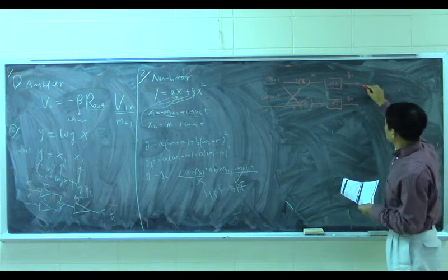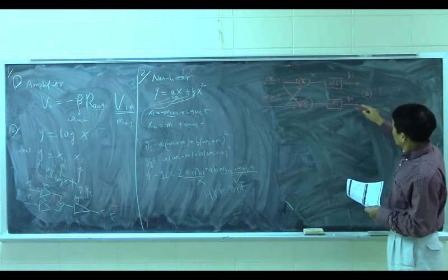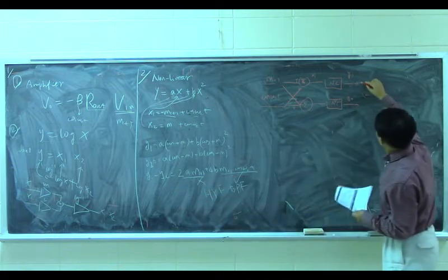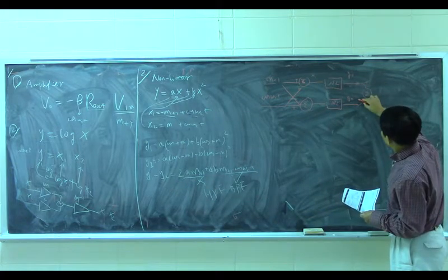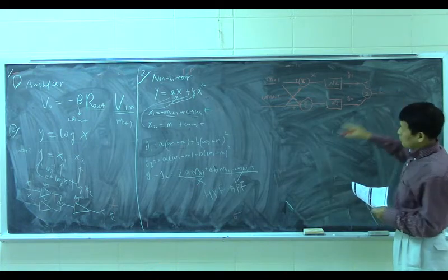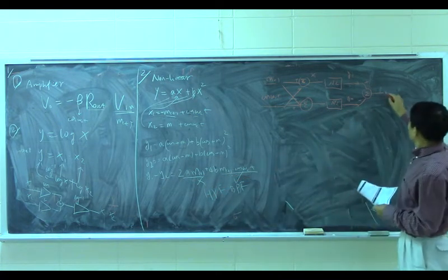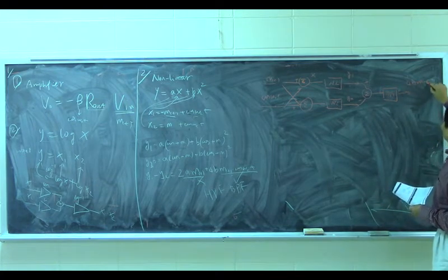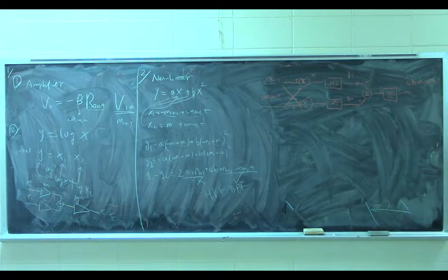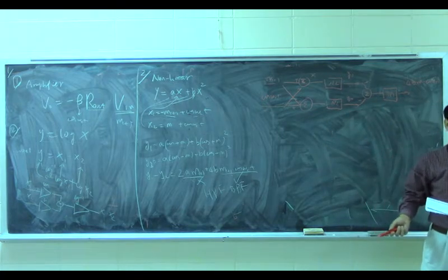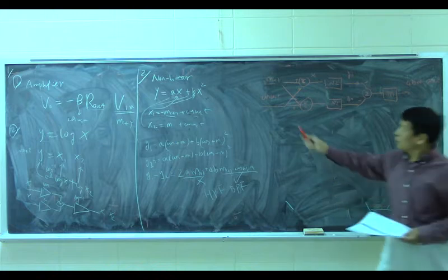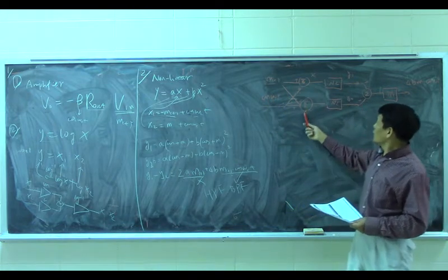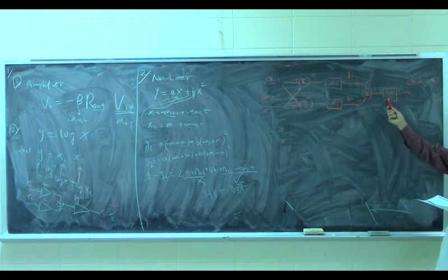Right? Now we need to use an adder here again. And we use Y1 minus Y2. So this one is positive, and this one here is negative. Then we get this part. And we need to use a band pass filter. Then we get 4B times MT times cosine omega CT. Right? That's it. That is what you need to do in the lab to implement this. You give me these two signals. I have an adder here, a nonlinear device here, and an adder here. Okay, band pass filter. Now this one is your output.